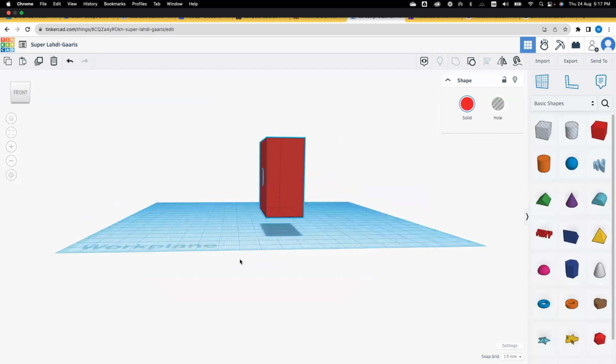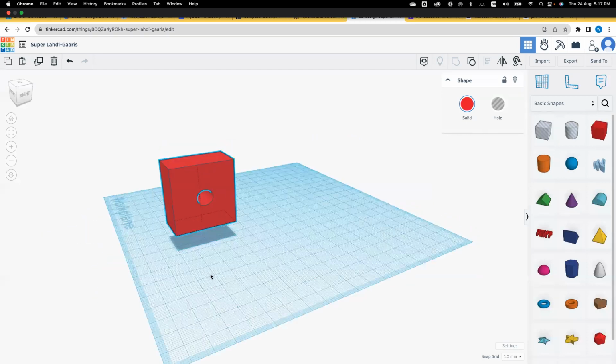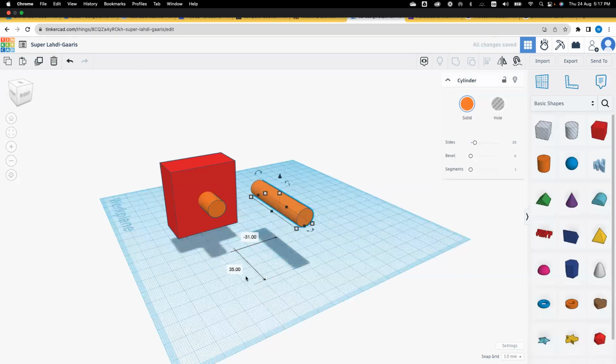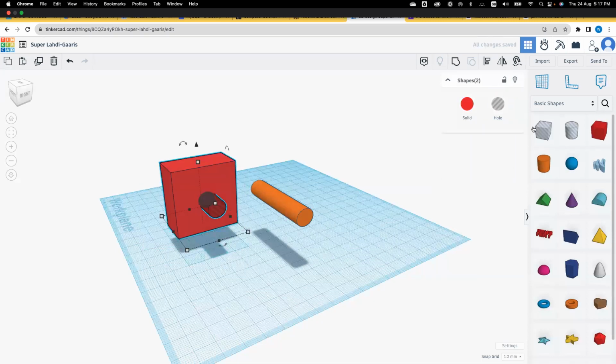The hole is created. But before, because I have in mind a specific manipulation, what I will have to do is to copy paste. I place one aside. I select the first. I click on hole. I select both items, and then I group. I don't know if you are working in parallel with me. I don't know if you can share the screen or split the screen. Anyhow, the session is recorded, so you can watch it in case you need some support.